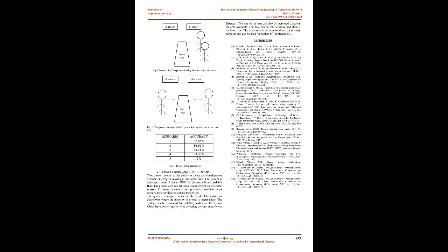When a person exits and passes through the mat, the weight of the person is converted to an electrical signal, which surpasses the threshold and is set high. The person then passes by the IR sensor, which detects the exit. Now, since both the sensors, piezoelectric and exit IR sensor, are set high, the system detects the person is leaving and the count is decreased by 1.